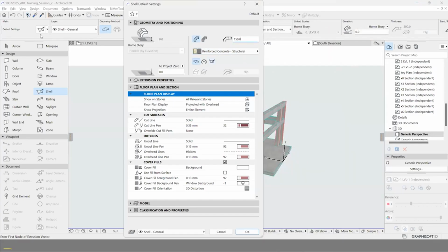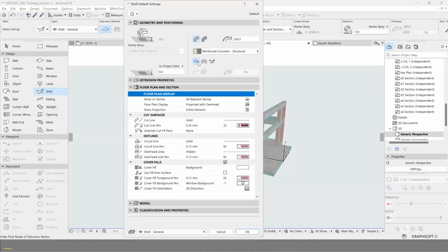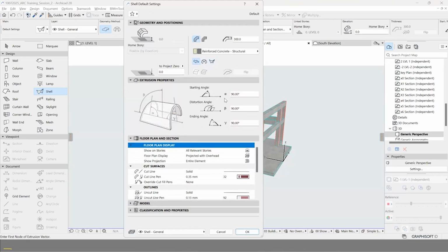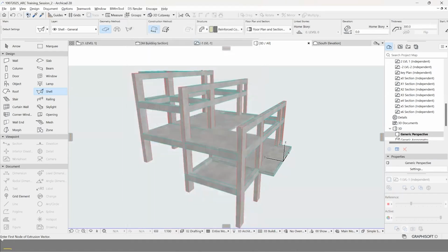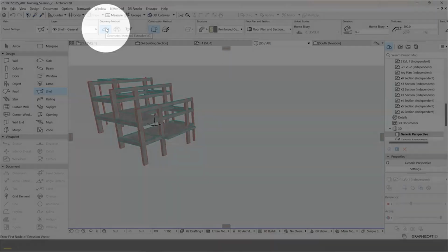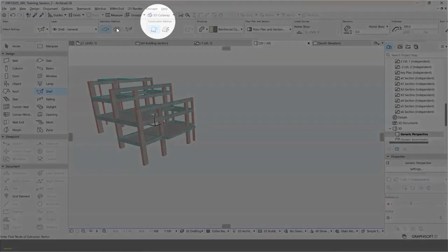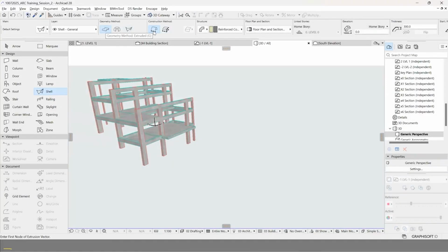And these are the 3 different structures I mentioned. The first one is the extruded method, the second one is the revolve method, and the third one is the ruled method. We will be looking at the first option. We won't be going much into these dimensions for now. Right now, the system asks for the first node of the extrusion vector. Even though I selected the extrusion method, ArchiCAD gives you a little more freedom through something called the construction method. For each of them, you always have two construction methods. One is a simple method.